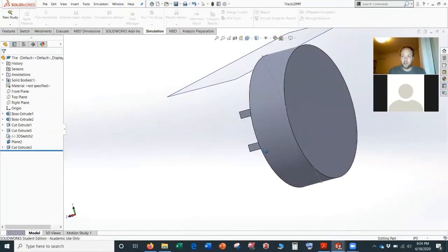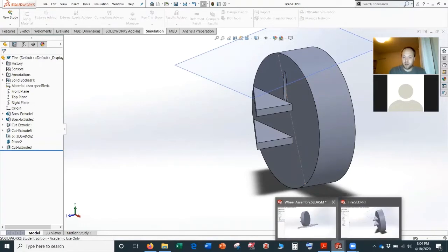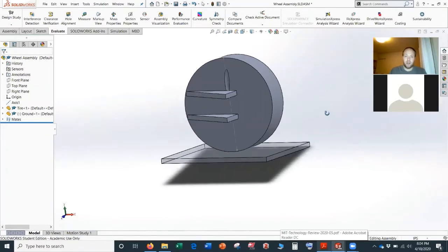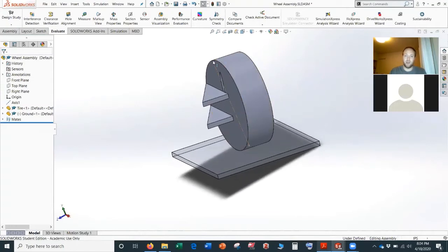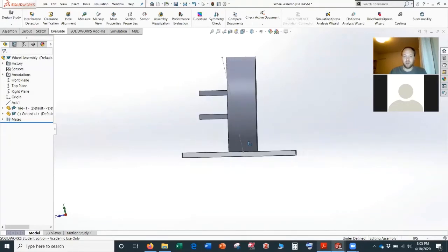All right, so let's look at how some of this will affect the tire and its interaction with the ground. What I've basically done is I've made a tire and I've made the ground and I've drawn the steering axis, also known as the kingpin axis, which would connect the upper and lower ball joint. You draw a line between those two, right? Obviously I intend them to go through these two spots on a fake kingpin sticking out, but in this one I wanted to show a case where, let's first just look at kingpin and scrub radius.